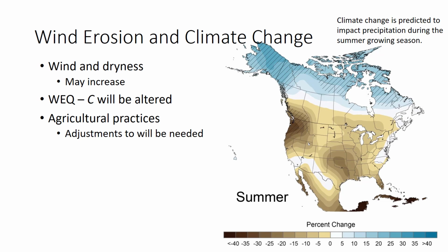In conclusion, wind erosion is more likely to occur on soils that are high in fine sand or silt and in hot, dry, windy conditions. Control practices include breaking the wind, keeping the soil rough, and planting at right angles to the wind. The most effective method is keeping the soil covered by vegetation or crop residues.